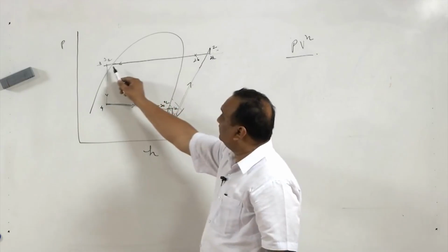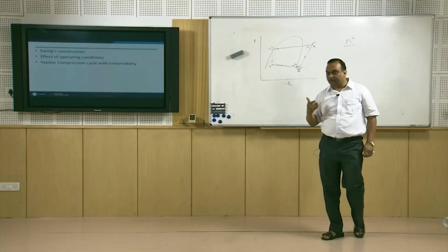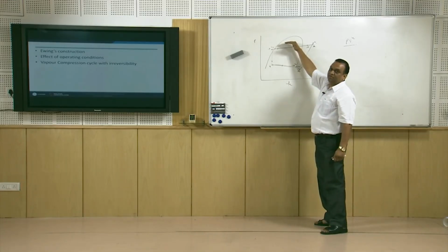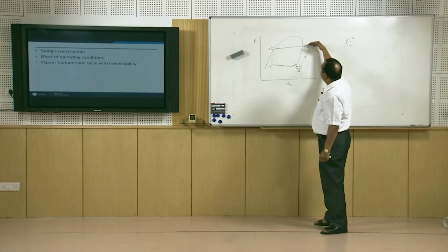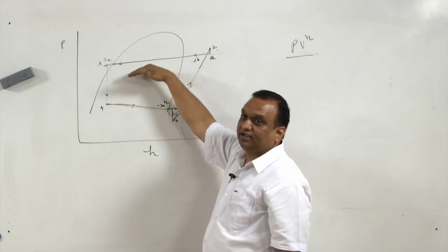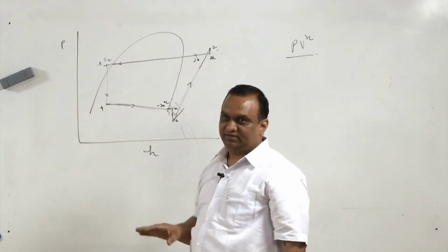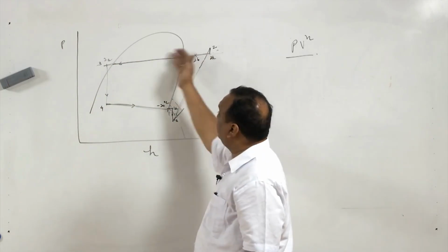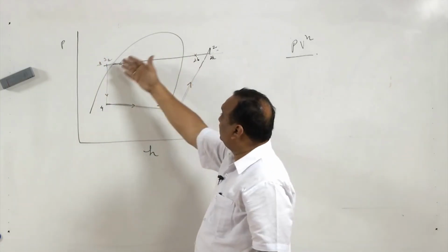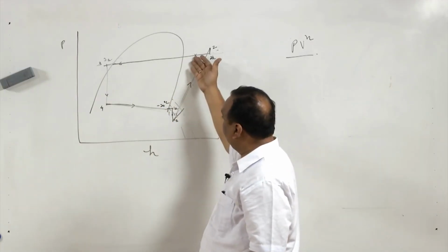However, in the case of the condenser, condensation is taking place and the kinetic energy of the fluid is reducing, which is being converted into pressure energy. So, pressure should rise here, but at the same time pressure loss is taking place due to friction. Both these effects compensate each other and sometimes there is a pressure rise in the condenser. Normally it does not happen, but it can. It means the conversion of kinetic energy to pressure energy is more than the loss of pressure due to friction.